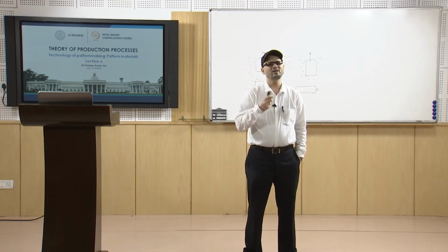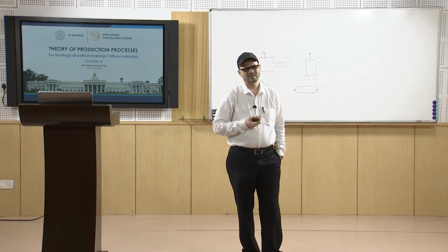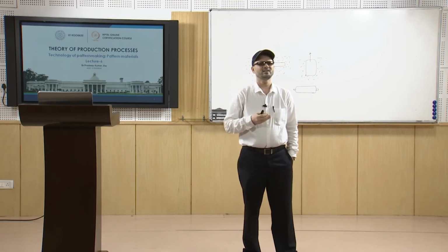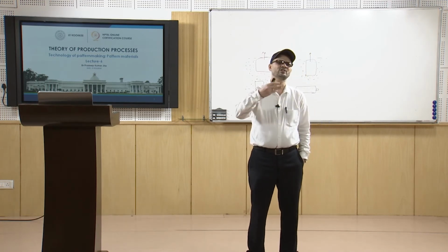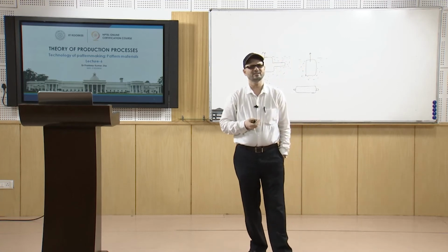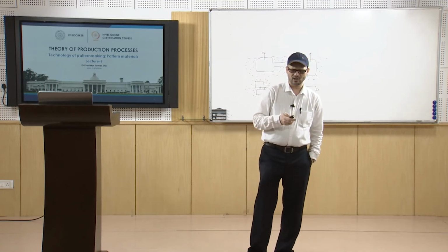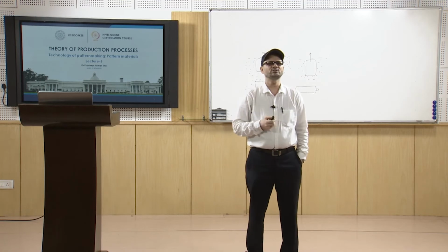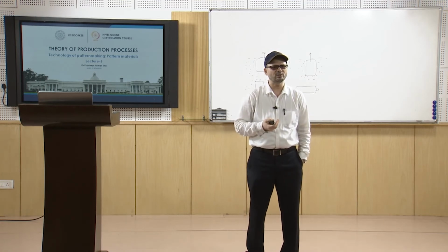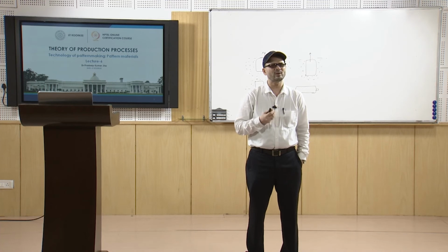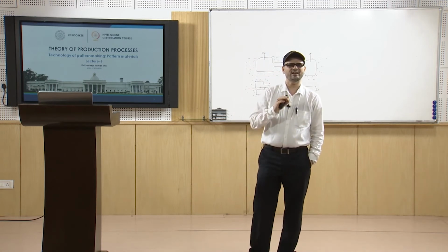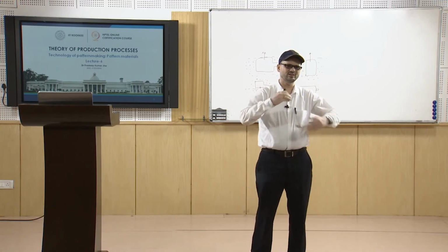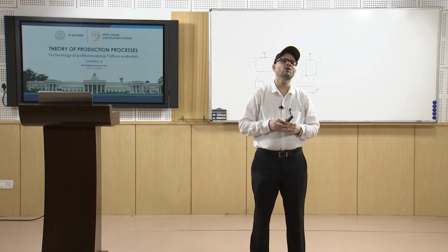Normally we use different kinds of wood: pine, mahogany, teak, walnut and deodar, and they have different properties. Pine wood is light, easy to work and able to take a good finish. Mahogany is a hard, strong and durable type of wood with negligible shrinkage or swelling after seasoning. It takes a very fine natural polish, stains well and glues excellently. So, these are the qualities of mahogany wood.